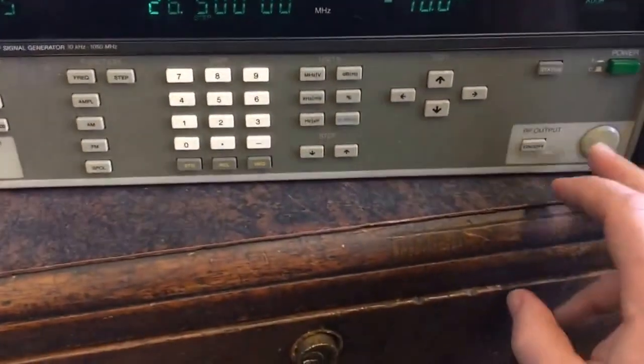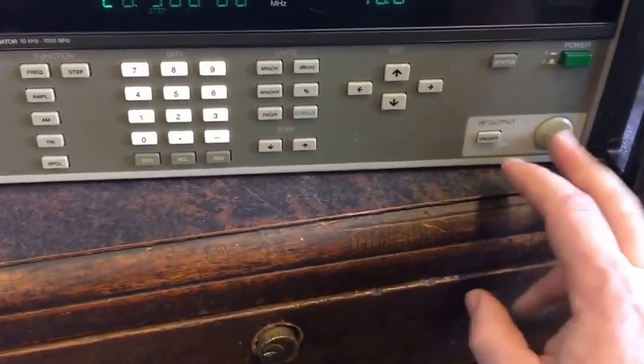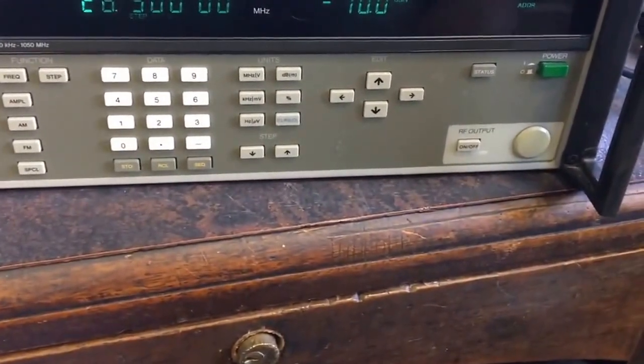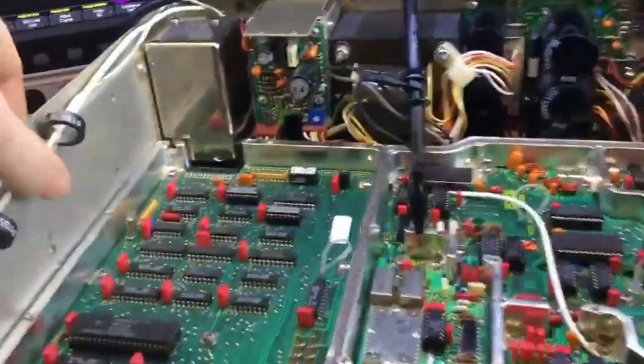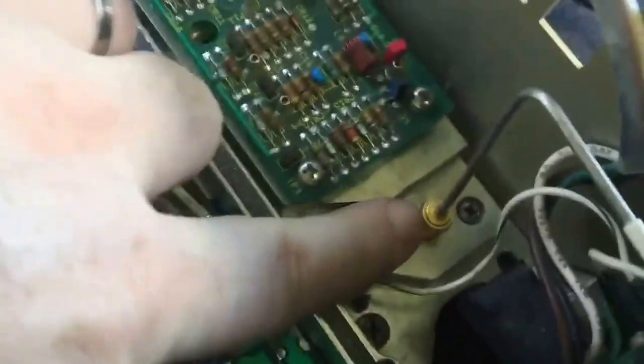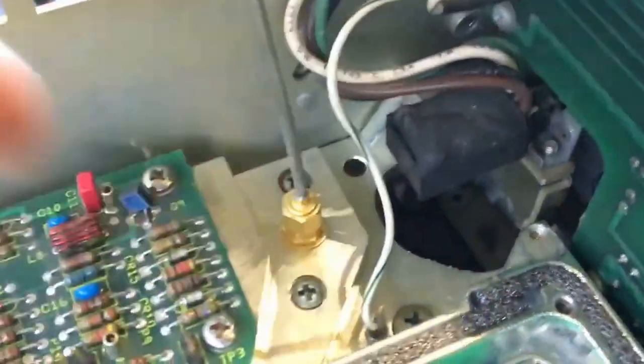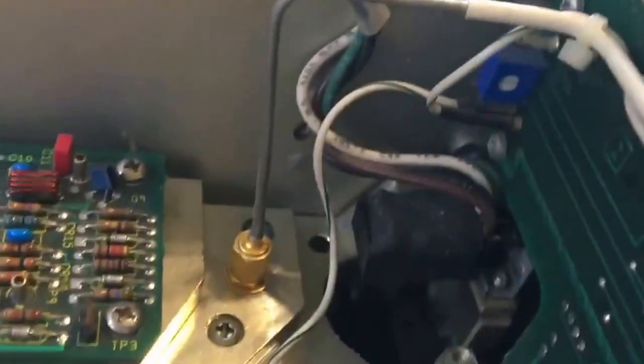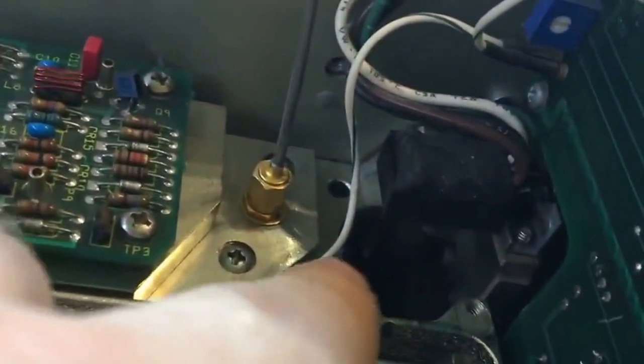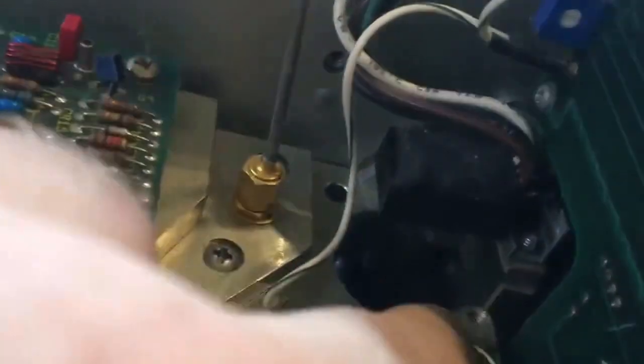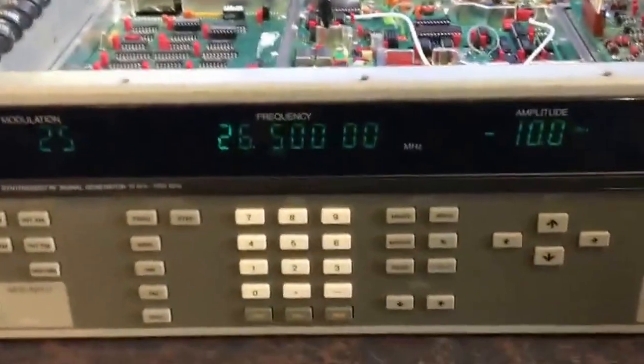Anyway, what I'm going to do, I'm going to open up this port on the front. I've ordered some sockets. I'm going to keep the original all intact because it's got this hard coax on most of the back. It runs down there. From the front, it comes out at this point, just here. So what I'm going to do, you can see where the socket goes just down there. I've ordered some SMA cable and a jack to go in there. I'm just going to unplug this, put the jack on, and run a little SMA cable between the two. And it's only going to be a few inches long, so I'm not too worried about any losses or anything like that from it, or shielding problems.